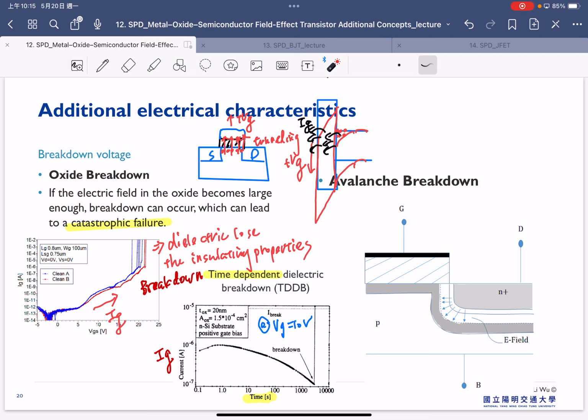As long as you have a structure related to dielectric-metal or dielectric-semiconductor, you will always face the TDDB issue. In this class we won't talk about TDDB too much, but in my other class related to reliability, we will talk about TDDB in a very comprehensive way, from the fundamentals to very advanced knowledge, also including lifetime fitting. Okay, so that's one of the issues for breakdown.